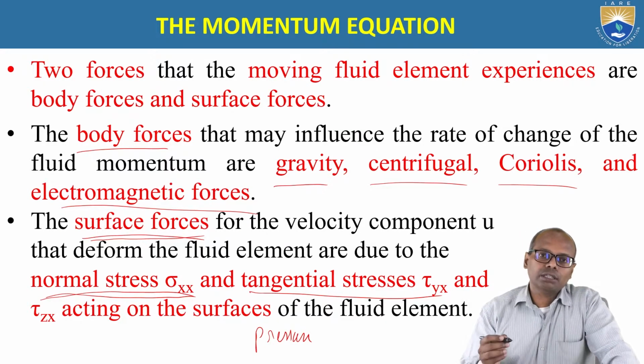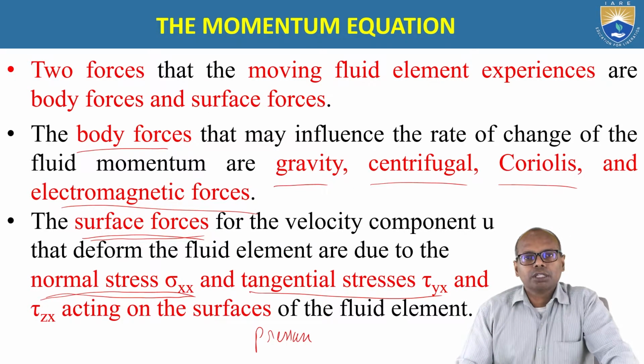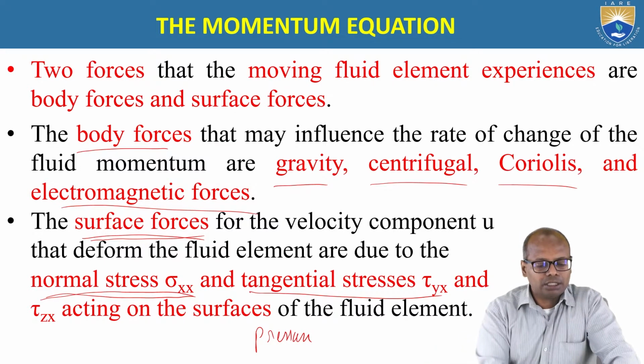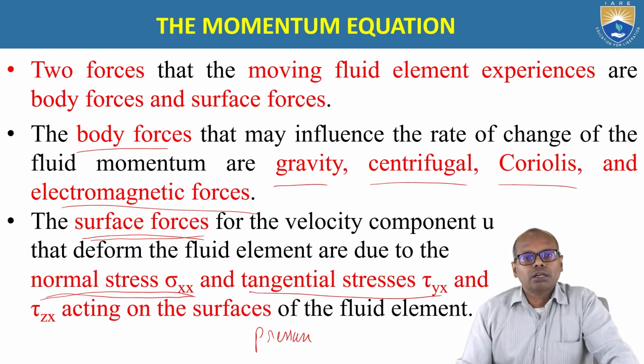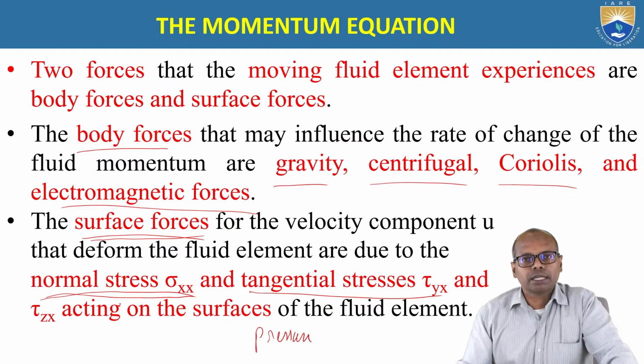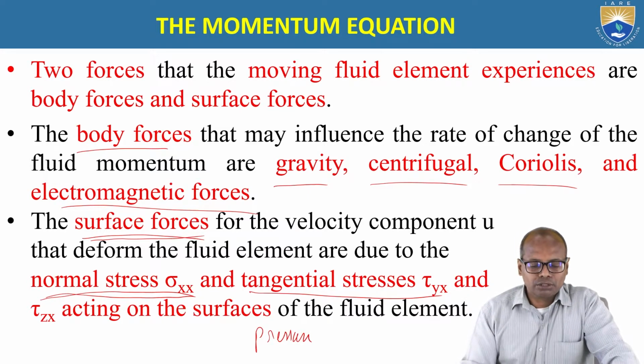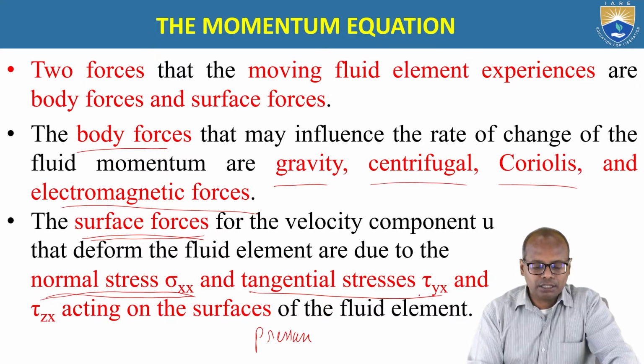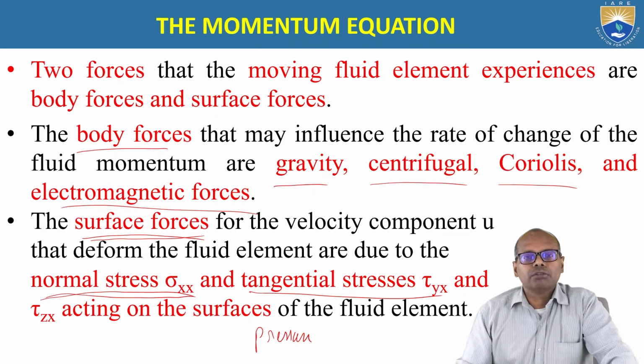Now the normal stresses are generally negligible. Only in cases like a shock wave, where the velocity gradient is very high in the normal direction, are the normal stresses counted in the calculation. Otherwise the normal stresses are neglected. Generally, only the tangential stresses and pressure forces are considered for the general cases of fluid flow.